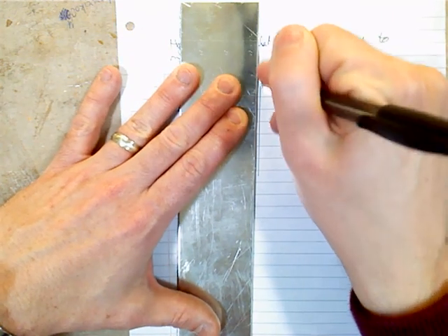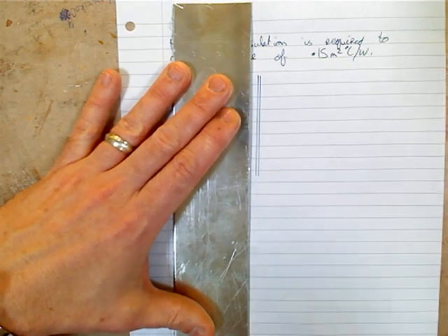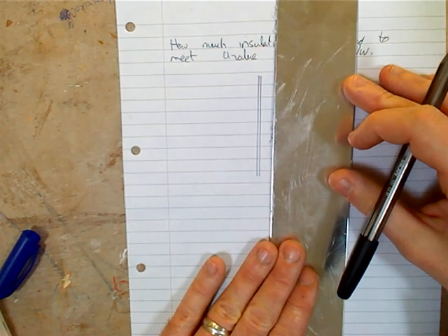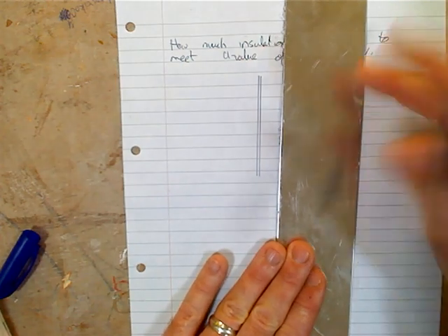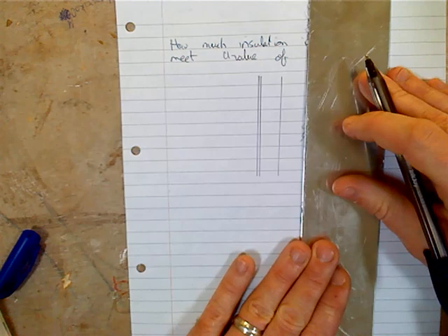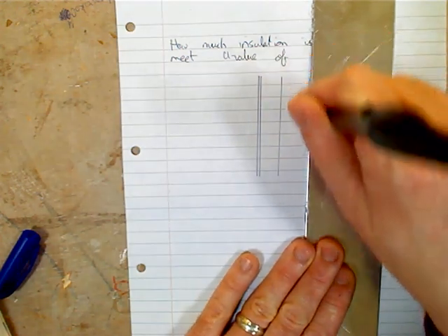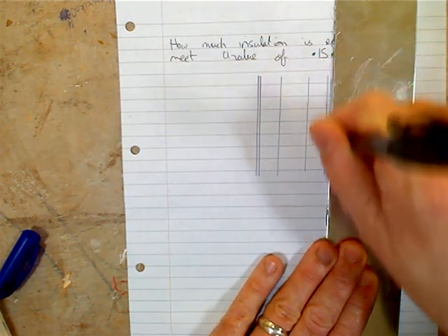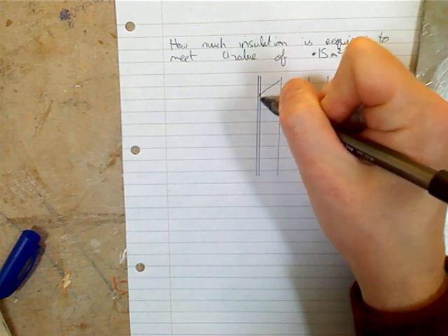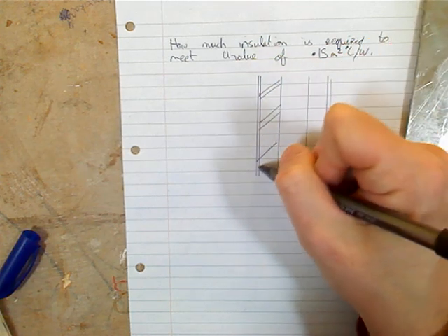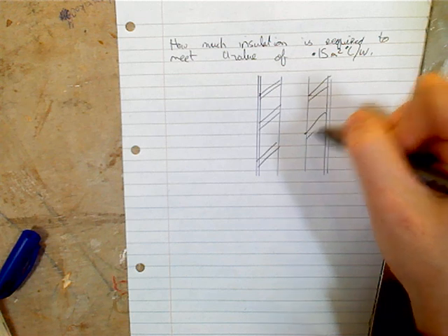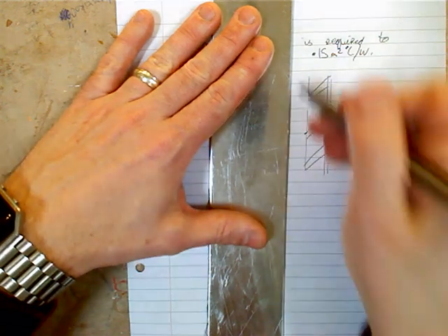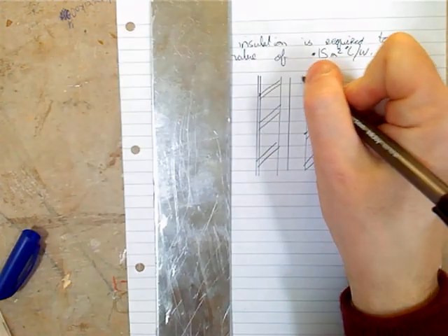So depending on where you want to put it, I'm going to put it on the inside just because it's easier to do. So we'll have our concrete block, we'll have our cavity which has a fill of insulation in it, we'll have another concrete block, and we'll have our internal plaster. So our hatching identifies that this is concrete, this is concrete. I have my insulation coming down the middle. This was our previous house.